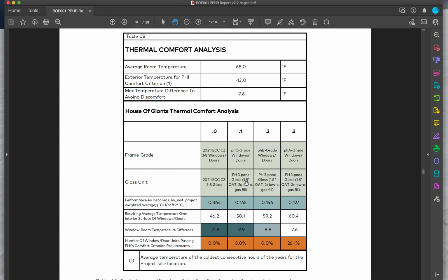This glass here is almost 2 inches thick, meaning that I have a lot more protection and a lot more insulation because I have much thicker glass pockets, not the glass pane itself, but the whole glass assembly comprising the 3 panes and the 2 glass pockets filled with gas, argon gas, not air, and 2 low E coatings. So this is something we can cover later.